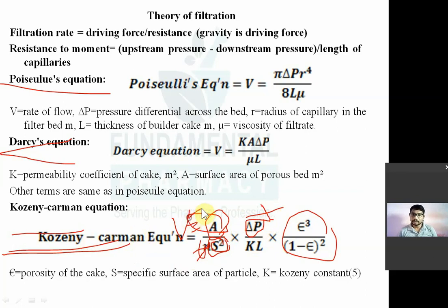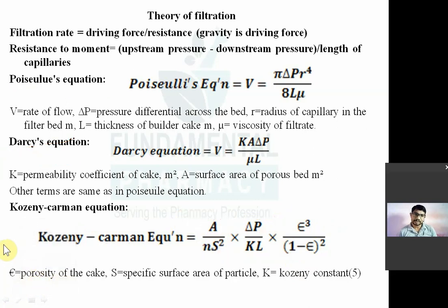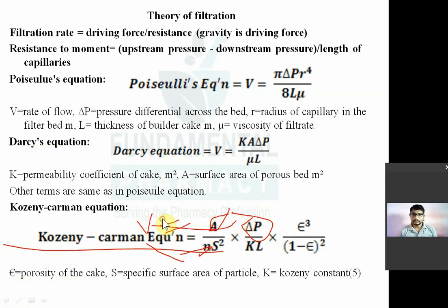जैसे filtration medium के ऊपर से, जैसे फोर्सफुली अगर आप स्लरी इंट्रोड्यूस कर रहे हो, दैट मीन्स देयर इज अ पॉजिटिव प्रेशर, सो प्रेशर डिफरेंशियल वहाँ पे ज़्यादा है, और बिलो द फिल्टर मीडियम इज लेस, so obviously rate of filtration will be increased. Okay, so either you can increase the rate of filtration by forcefully introducing the slurry, or you can decrease the pressure below the filtration medium by using vacuum. So you can apply vacuum, there will be increase in the pressure difference, there will be increase in the filtration rate.